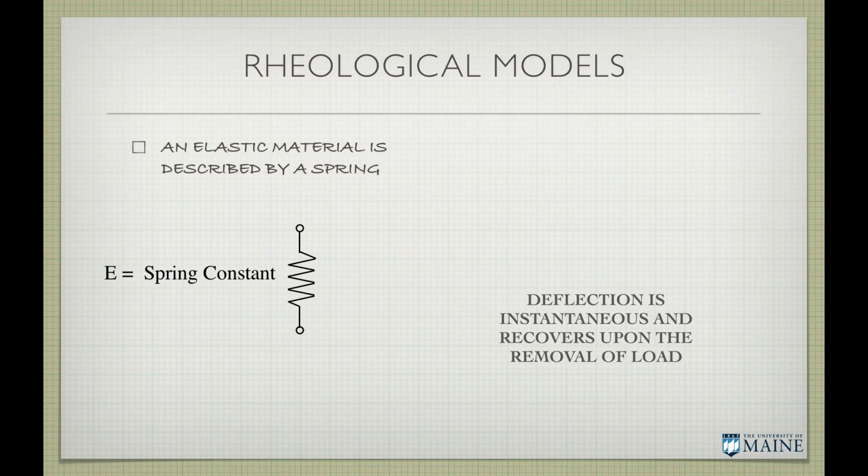And you end up with differential equations, or a series of coupled differential equations, to describe the behavior. It is the exact same thing that an electrical engineer would use to describe a circuit. Same mathematics, different interpretation of what the components are. A spring, an electrical engineer says, is a resistor, but the math ends up being the same. They talk about voltage, we would talk about deflection. So you get these analogies.